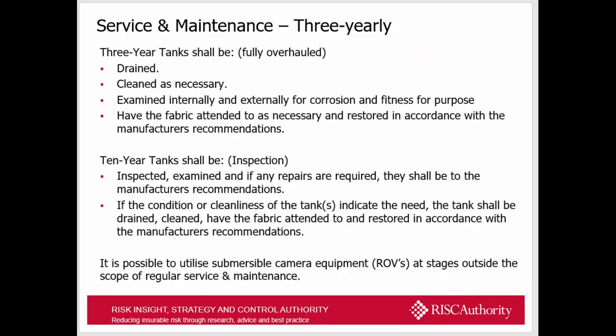So 3 yearly tanks. They shall be drained, cleaned as necessary. They shall be examined internally and externally for corrosion, fitness for purpose, and have the fabric attended to as necessary, and restored in accordance with the manufacturer's recommendations. So every 3 years, if you have a 3 yearly maintenance-free tank, you must drain that tank fully, clean it as necessary, and get the tank as near as possible in accordance with the manufacturer's recommendations.